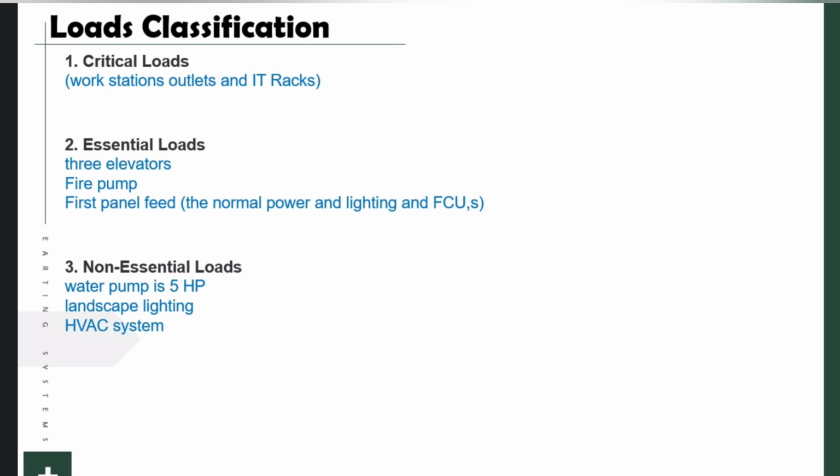In the beginning I make the load classification. I classify the load into the three categories of load which we were talking about in the previous lecture. For the critical load I choose the workstations outlet and the IT racks and everything related to the IT or communication system. And for the essential load, I chose the three elevators and the fire pump, in addition to